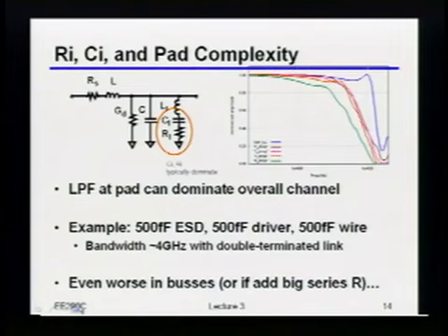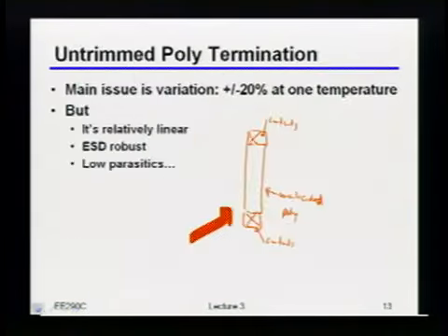Yeah. I mean, for the on-chip resistor, it's not just the unsilicided poly. You can do some kind of long metal line, which would have more. Okay. So you could indeed do a long metal line. If you do a really long metal line, the problem I think you'll run into is that this particular statement I'm making here will no longer be true. Because if the metal has to be 110 millimeters long or whatever it is, and I snake it around 20 times to get a few kilo ohms, it's probably going to be pretty big and have a lot of capacitance.